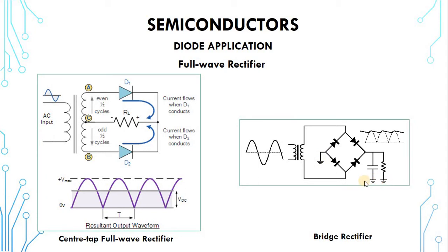So it tells you that they are all interconnected and they are at the same potential. So in this case, we have seen that when the top is positive and the bottom is negative, this diode conducts the positive to the terminal of the load, positive here, and then this diode allows the negative to arrive at the ground here. So for the first half cycle, we have positive here and negative here. Let's see what happens when it alternates.